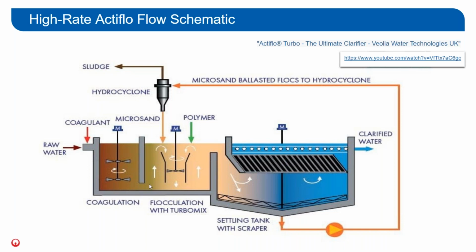And we have an underflow to either an injection chamber or just one flocculation chamber, where they start to marry with the polymer, as I said, a good coat on the outside of that sand that you're adding either through new bags or, more regularly, the microsand that is being added through the underflow of your hydrocyclone.